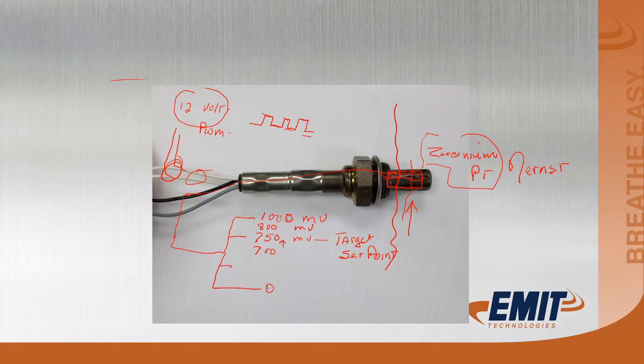Once we get down into really low numbers, say below 400, below 300, it is no longer linear. It's not accurate at all anymore. These numbers are nothing that you would want to rely on. All you know at that point is that the engine is really lean. There's not enough unburned hydrocarbon in the exhaust. It's not rich enough for this little catalyst to have enough electrons discharged to it to produce that millivolt reading. Very simple. It's just a little catalyst.